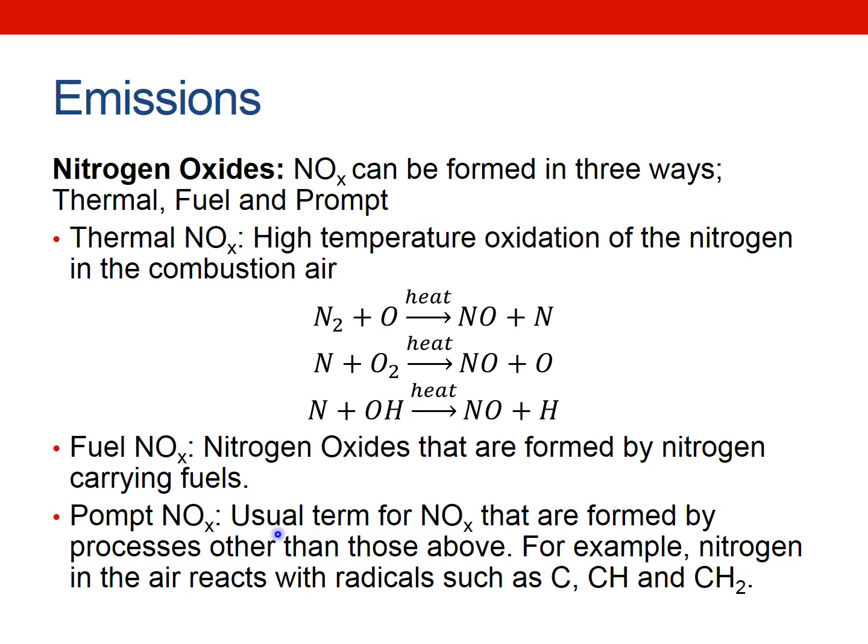And the last one is prompt NOx. Now this is kind of the usual term for NOx that are formed by processes other than those above. It's almost like a miscellaneous one. But one example is the nitrogen in the air that reacts with radicals such as CH and CH2, etc. So it's not formed by temperature, and it doesn't come from the fuel, but it's formed by these other free radicals.